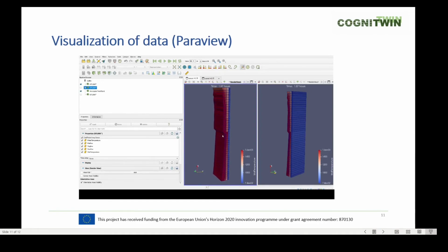And we can have a look at how the temperatures evolve if you're looking at the transient. So we see here that the temperatures in the refractory at the time just before filling the metal into the ladle is a result of the history of this refractory, how long time since it was last used, and also how long time it has been passing since last use until the next use.